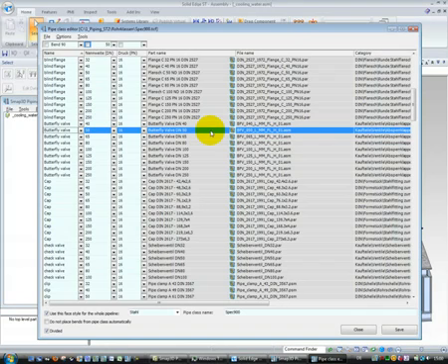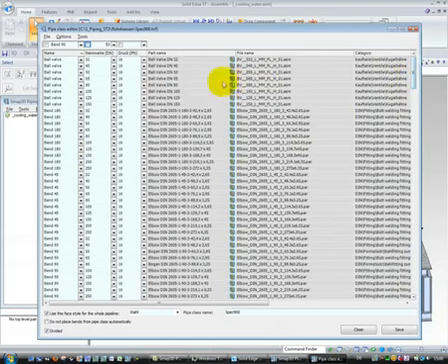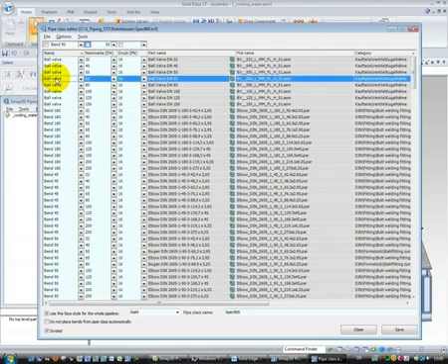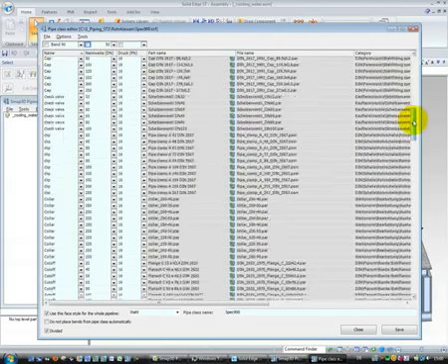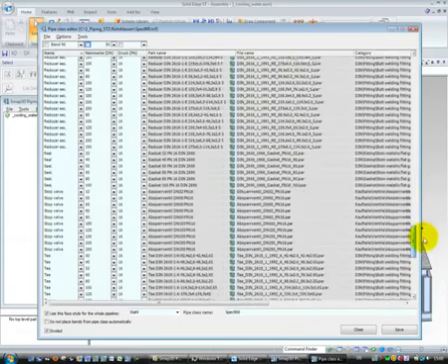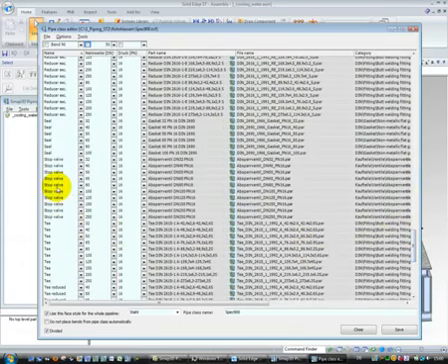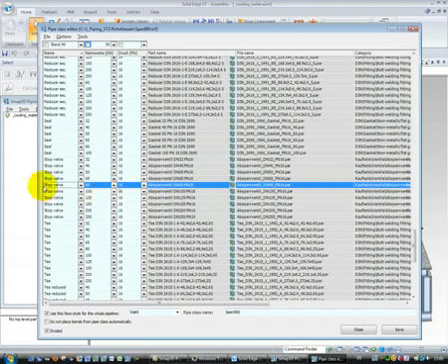a new 3D pipeline. In this case we have a butterfly valve, or similar to that you can specify ball valves or any required keyword, we call it keyword, for example stop valve. That means the component which is specified here with such an additional keyword will be used in a later step, at the creation of the 3D pipeline, by the user when he places it additionally.